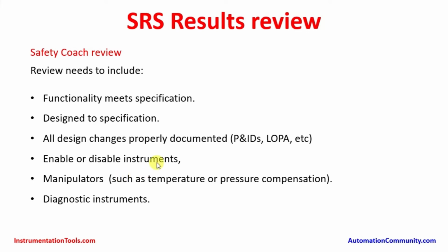Enable or disable instruments. Whenever any instrument needs to go for bypass, that has to be disabled. These things are to be captured in the procedures which the safety instrumented system coach will review. And manipulators such as temperature or pressure compensation. If any instrument needs pressure or temperature compensation, that has to be updated. Diagnostic instrument details have to be updated. So these are the different checkpoints the safety instrumented system coach will review.